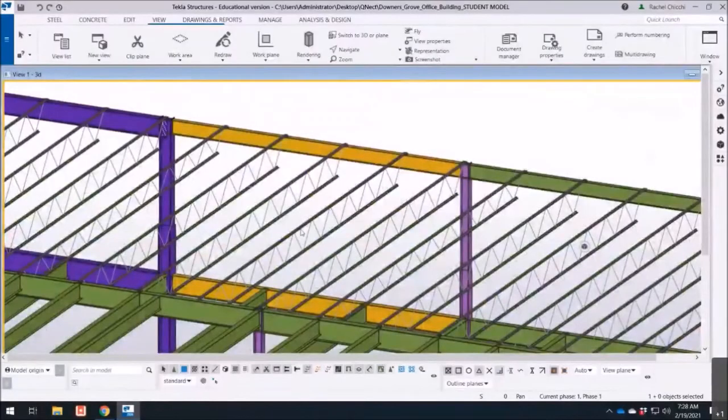At the roof, you'll see steel joists shown in gray. These are open web, lightweight steel trusses. They are typically able to span long distances and allow for utilities such as plumbing, conduit, and occasionally small ductwork to run through the members. However, joists may experience more vibration issues than traditional hot-rolled shapes like wide flanges. Roof loads are usually less than the floor loads, and vibrations are not typically an issue at the roof, so using joists as roof framing is somewhat typical.